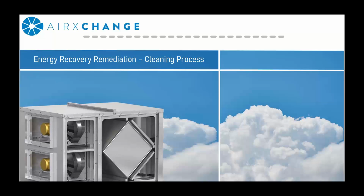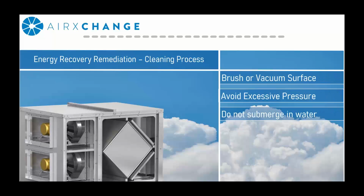The cleaning process for the air exchange plates is a little different. For the plates, we don't recommend that you wash the media, just do a dry cleaning using a vacuum. You're going to want to gently brush and vacuum the surface area, taking care not to exert too much pressure, because you wouldn't want to damage the device. And just like the wheels, we recommend that you take the component outside of the cabinet to perform the cleaning process, as it provides a more hygienic approach, so you don't introduce any potential contaminant into the HVAC stream.